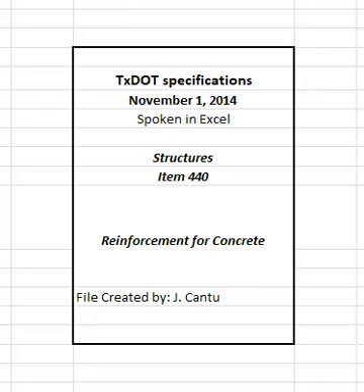Rust, surface seams, surface irregularities, or mill scale will not be cause for rejection if the minimum cross-sectional area of a hand wire brushed specimen meets the requirements for the size of steel specified. Do not allow stainless reinforcing steel to be in direct contact with uncoated reinforcing steel, nor with galvanized reinforcing steel. This does not apply to stainless steel wires and ties. Store stainless reinforcing steel separately, off the ground on wooden supports.